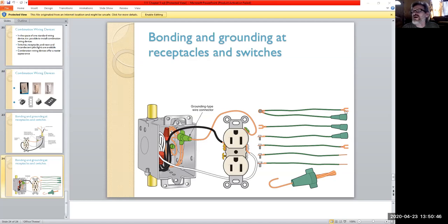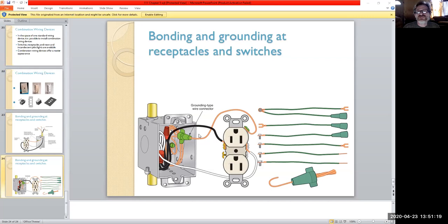And there's different ways, as long as you're bonded with ground, how you connect up. You can have the crimp on with the little spades, right, like that. Or even the little spades coming in from the ground connector going out. There's different combos, but as long as you got it bonded correctly, going to the device that you need to. And in this day and age, see, this is a metal box, right? But a lot of them now we're dealing with plastic, so you wouldn't even have the bond screw inside there like that. So you'll probably be splicing and going directly to the receptacle.